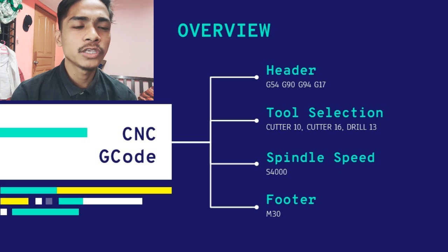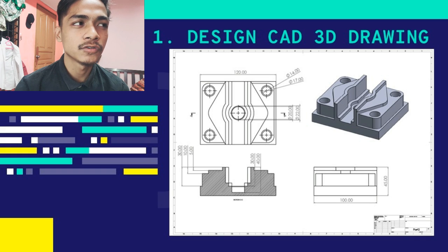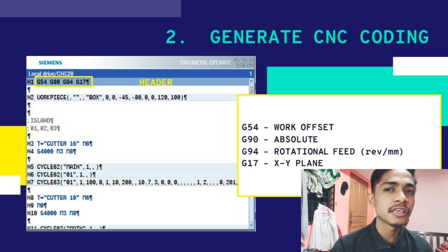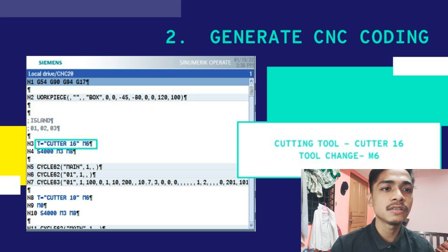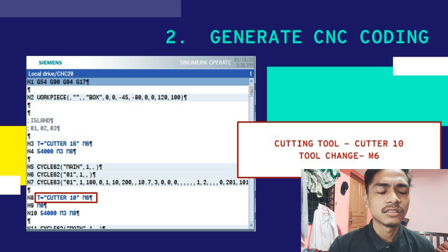In design, we use a CAD model, using SolidWorks for 3D modeling, and then we generate the CNC code using SolidWorks. Then we set up the CNC code and review it using simulation in milling, and then we run the CNC code in the milling machine, executing the milling machine process operation using the CNC code. Thank you.